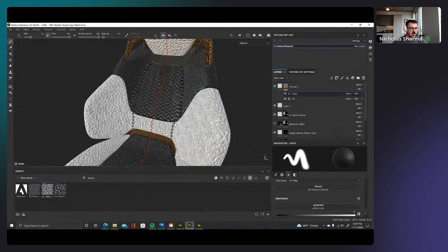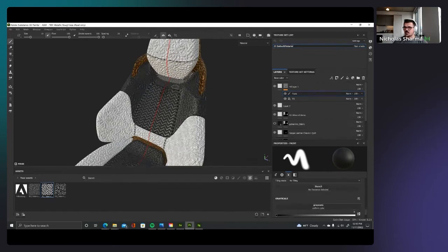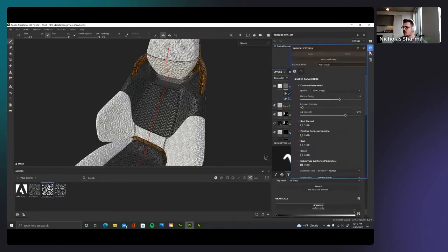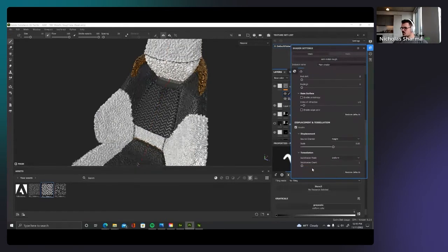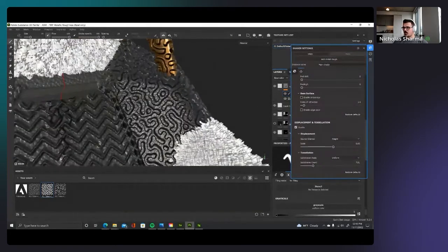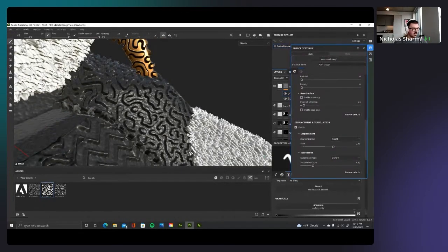If you come from the footwear industry as well, having these graphics and applying them to your outsole will save you a ton of time, because you can extrude these graphics and this height information off the surface. So for instance, if you were to crank up the displacement for this and the subdivision count a little bit, and we look at the graphic that I applied here, it's coming off the surface because it's taking that height and displacement information and extruding that effect off of the model itself. What's nice though is that you can export this out and save this geometry with the displacement intact. So if you wanted to 3D print this, you can, and it will save all that information for you.